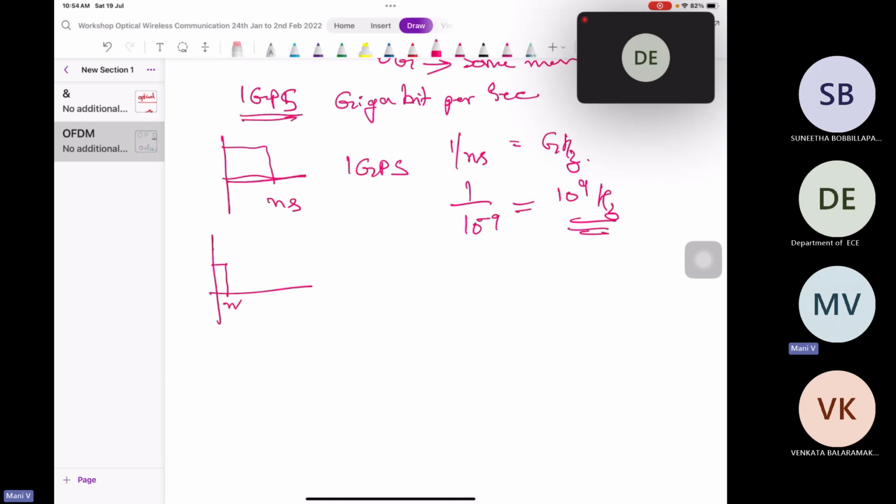This short time of nanoseconds, when it is received through your wireless communication channel, I will receive 1 bit of transmission. Apart from that bit, because of the reflections, scattering, diffraction and other effects, I will also receive some more signals like this at different intervals. Now what is this creating? Can I decode this signal now? What do I have to decode? I have to decode this signal, but if you look at it, it is now contaminated with many samples of information.